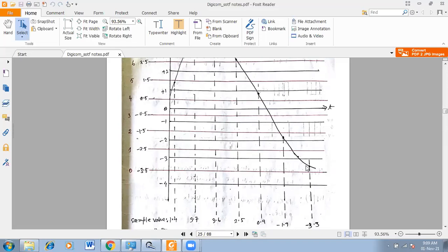Okay. So to find out quantization level, listen everyone, please listen everyone. So x of n means what has happened? You have got the discrete time signal, okay? But this amplitude may be any value. This signal could be from minus infinity to plus infinity. It could be minus 50 to plus 50. The signal strength could be minus 30 to plus 30. Whatever be the signal amplitude, peak to peak amplitude, you have to quantize by means of some particular levels.